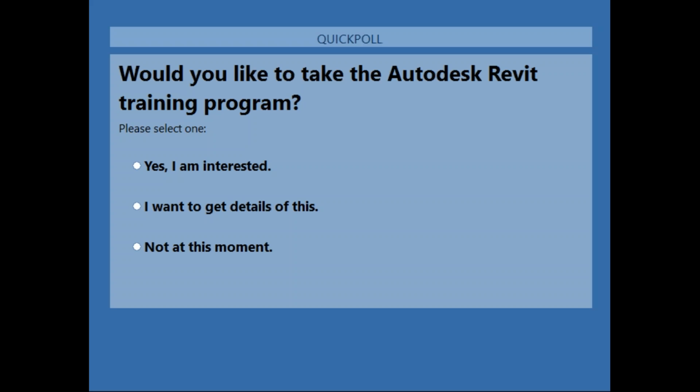And you notice too how I can apply that view template for the filters alone and then apply it to every single view, and then they will actually show those patterns or those color codings, whatever is the case.